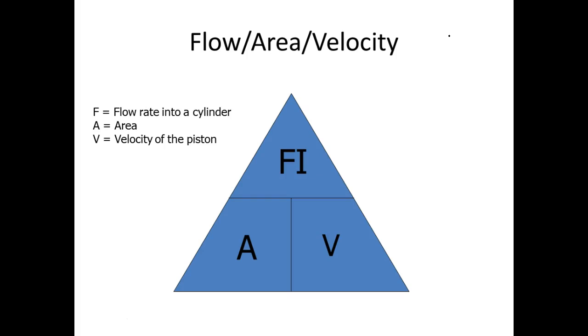What determines the force? Flow has nothing to do with the force. It's the pressure and the area. Speed is not in that formula. Velocity is not in the force formula. So force does not determine the speed. What determines the speed? How many gallons per minute you move, and then what area you're moving that against. So the bigger the area, the slower it's going to go.